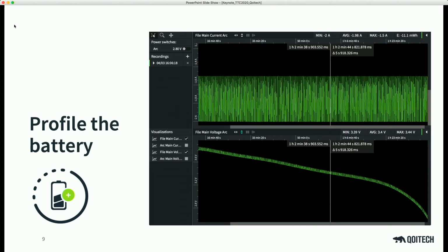So how do you profile the battery? Well, magic again, and that magic can be explained by the experts in our booth. What I can say very easily is that you connect your battery and discharge it for the specifications that you have for your own application, which means you're picking how the currents look, how often this is going to happen, the times, the levels of the currents, and you discharge it to the voltage that you want.